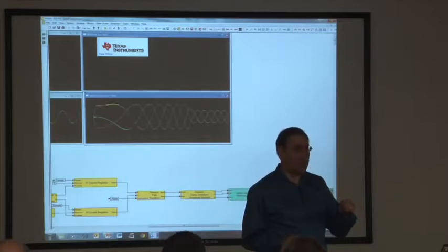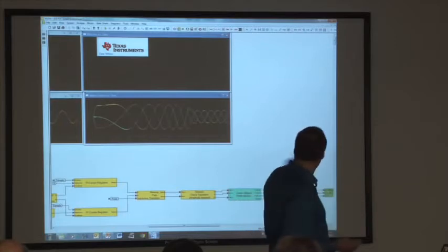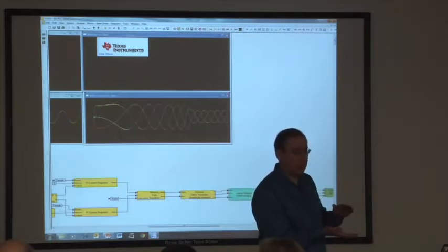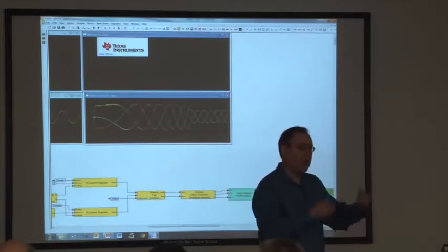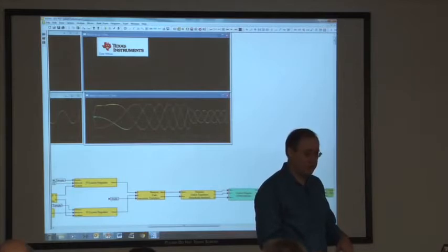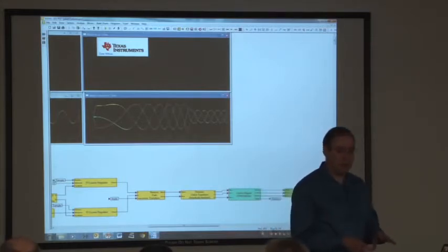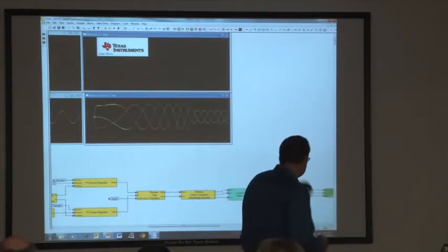So it can never request more than 20 amps out of the Q axis. What happens is, you'll see that the current waveform is flat-topped at 20 amps, which means that it's generating a constant torque. A constant torque applied to a constant moment of inertia J will equal constant acceleration.